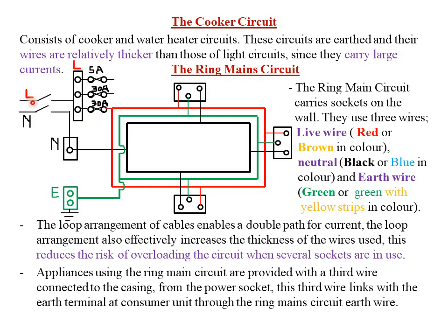Of course, this is the main switch, which has double poles. We have the neutral pole of this particular main switch, which will connect to the neutral wire here. Then of course the upper pole is what we call the live wire, which when closed, will connect with this other wire here. So you can see the live wire. Through the live wire, we are connecting these particular fuses.